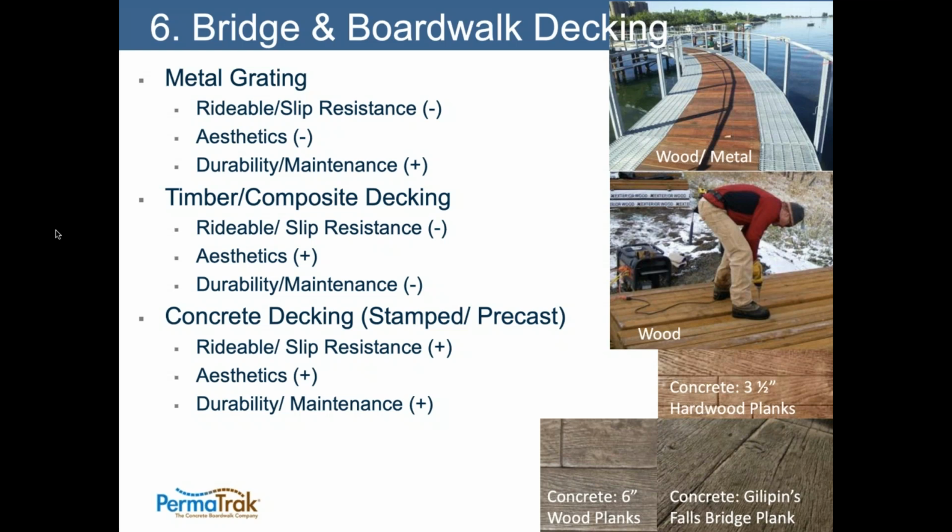The downside with the timber is the rideability and the slip resistance. As you know, it's going to be good early on in its design life, and over time it's going to get slippery, and the timber has a tendency to rot and twist and possibly decay over time. Durability generally gets a negative rating.